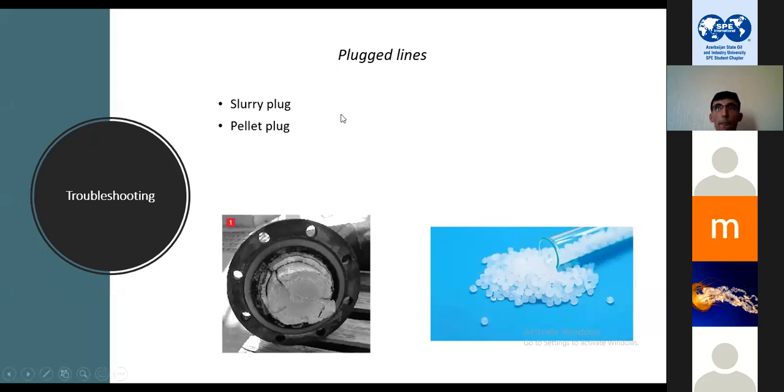And sometimes, because we have axial pumps inside our reactors, after an emergency some slurry can settle down because the pump stopped, and the pumps are still hot, so it can melt and cover all the pumps and impellers. Then we again have to open the reactors, dismantle and clean them. And it's a big problem.